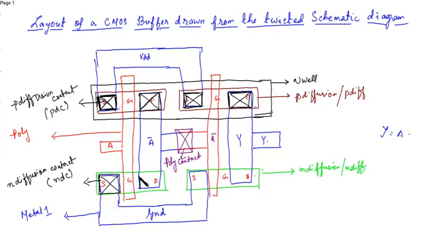Similarly over here, place one contact. Even in the NMOS we have got 2 junctions each, so there will be 4. If a junction is not connected or it has been placed in common P diffusion and N diffusion, then you do not require these contacts.